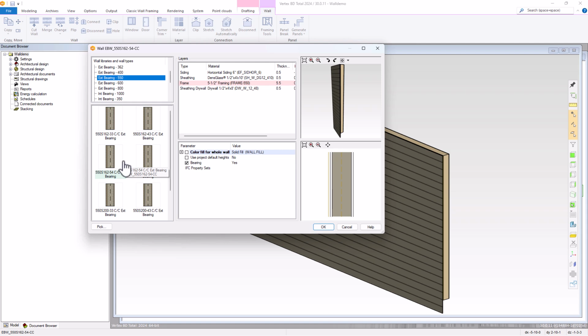A wall type is defined as a style of a wall. For example, a wall type can be a brick wall with layers such as drywall, sheathing, and framing. Another type could be a wall with vertical or horizontal siding that also includes layers that make up the wall type. Wall layers are materials that are part of a wall type that are used to create the wall style.